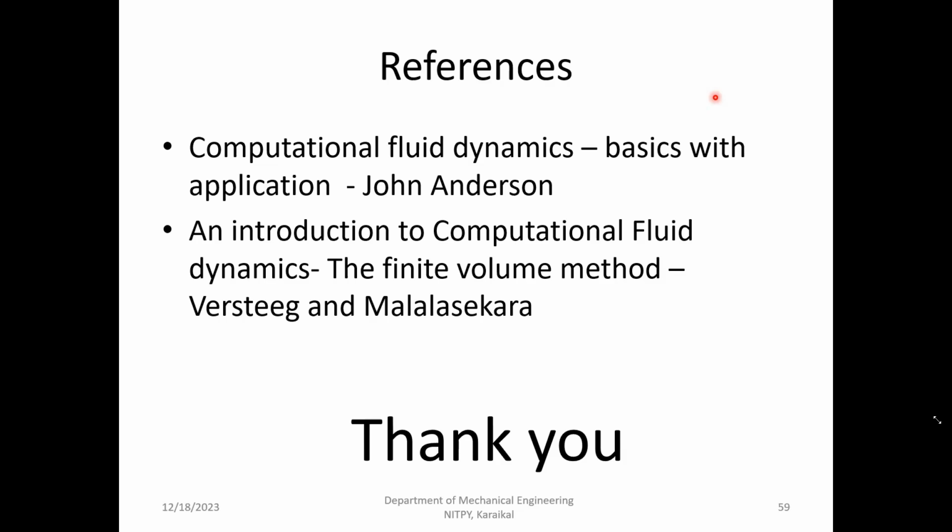Okay. Now when you're going to talk of errors in CFD, you'll be having 3 major errors that are inherent to the nature of CFD itself. First thing is, we are going to convert the differential equations into algebraic equations. So that is going to give you the discretization error. And then we are going to truncate the Taylor series. So that will give the truncation error. And then depending on the system we are going to use, 32-bit or 64-bit, we will be rounding off to that number of digits. So that's going to be a round off error. So all these errors are going to be there in our CFD simulations in the first place.